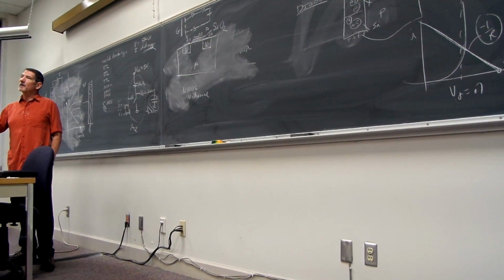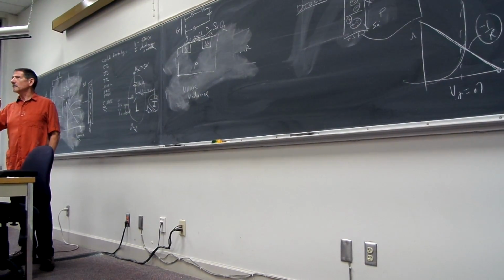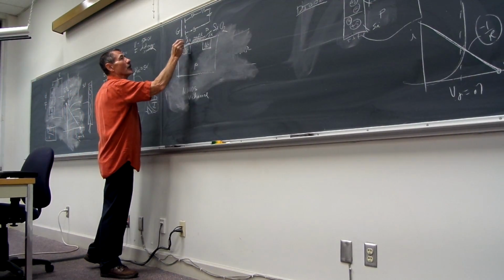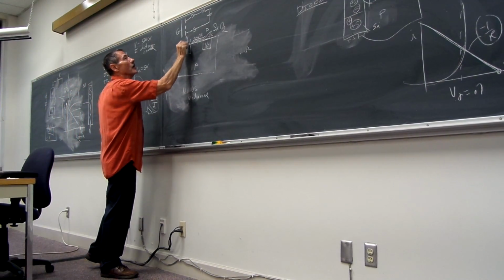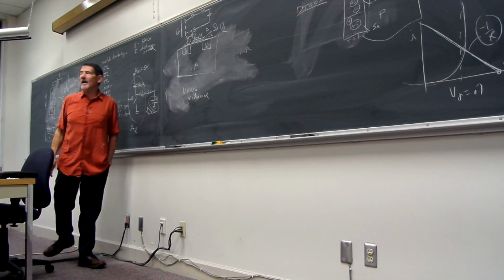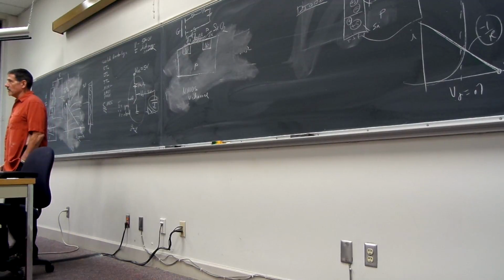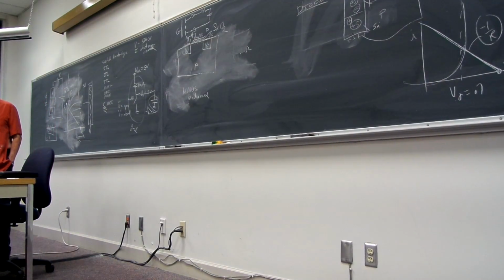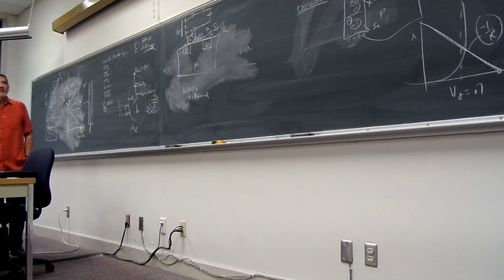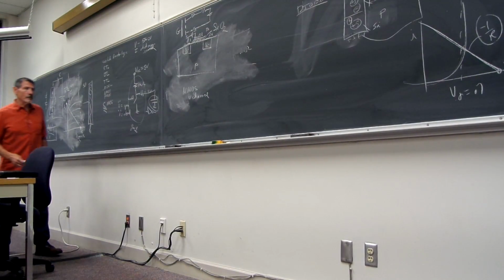So if I put a little bit of charge, a little bit of current. The more charge I put between the gate, so this is my source here, I'm going to put a battery here, like that, and now I can open up that channel. An N channel is induced, and current can start to flow.